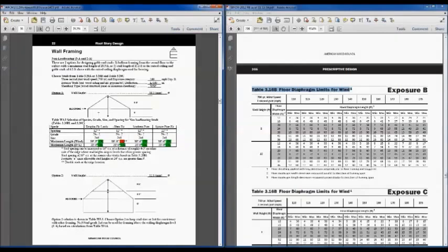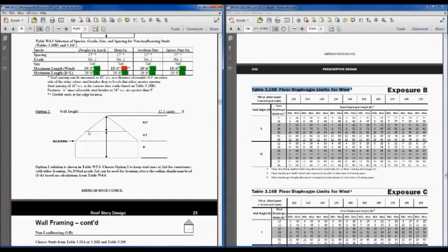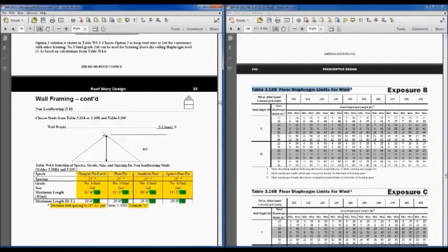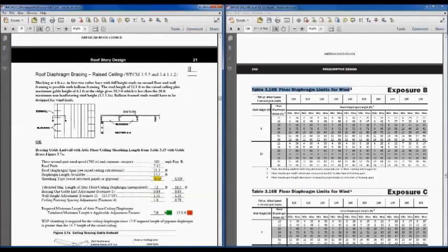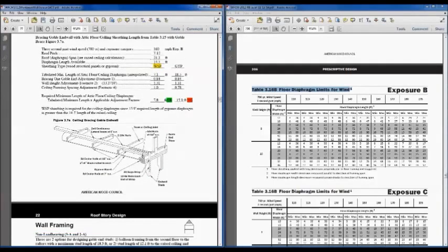So now looking at it from the other direction, the gable end wall, we're now framing the studs up to that location and probably putting a wall system here to correspond to that raised ceiling. And so that's creating a hinge here, which means we have to detail to account for those loads in that direction of the gable end wall as well.